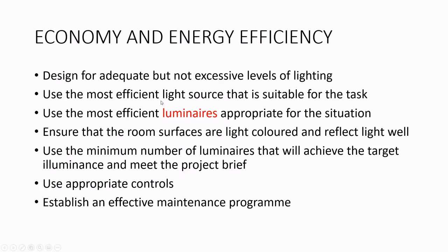And you have to use the most efficient luminaires. We are going to talk about what luminaires are, and this is an important thing. So you have to make sure that the surfaces of the room, that means walls, ceiling and the floor, are light colored. If those things are light colored, they reflect the light very well. So you can choose low power rated light bulbs to get the same illuminance levels.